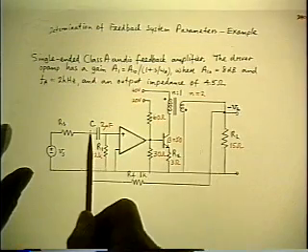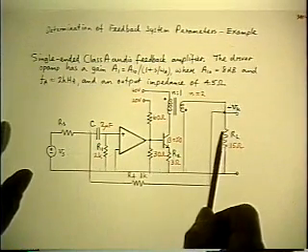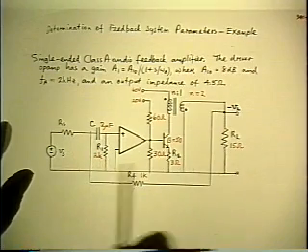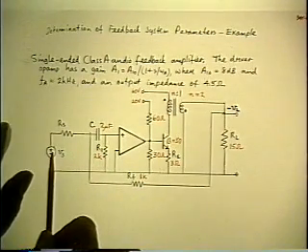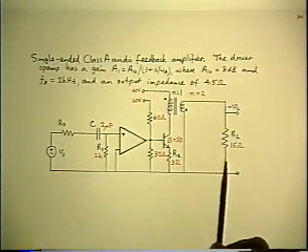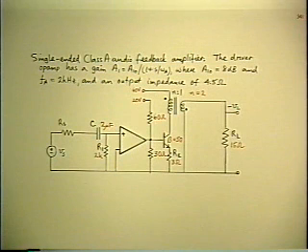Do you put RF to ground through RS, or do you put RF to ground through RS parallel the capacitor in R1? And even so, what about the VS? Because that's going to change the current down the path anyway. So you get into trouble when you start trying to fix up the diagram that you've already screwed up.